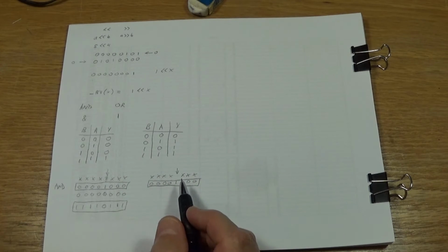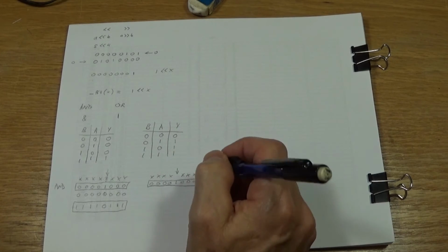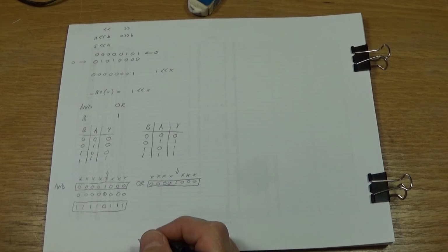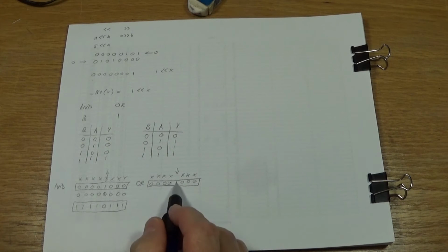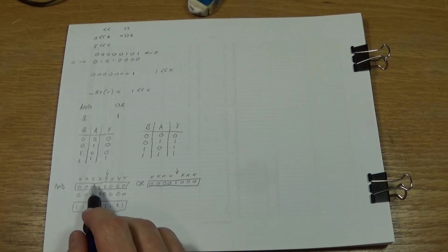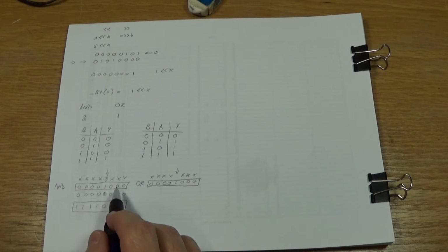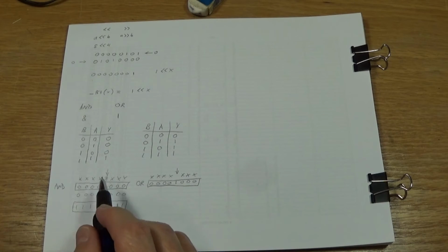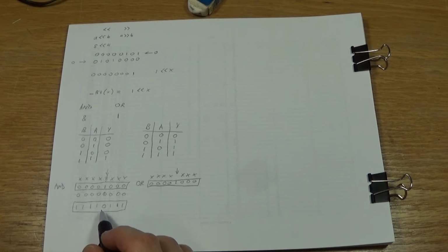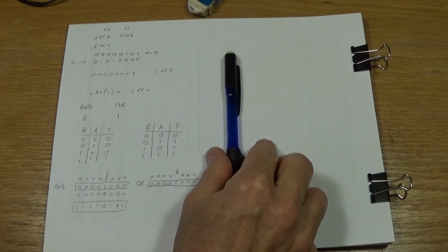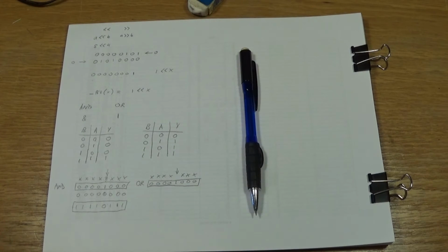Now, keep this in mind. This is the OR function here. Keep this in mind when we look at the software and how I've written the code, because I'm using both of these. I'm not using reading a bit yet. I'll probably show you in another video how to read a bit using a mask, but I want to set or clear a bit by using these ANDing and ORing masks. So we'll have a look at our software and see how that's done.